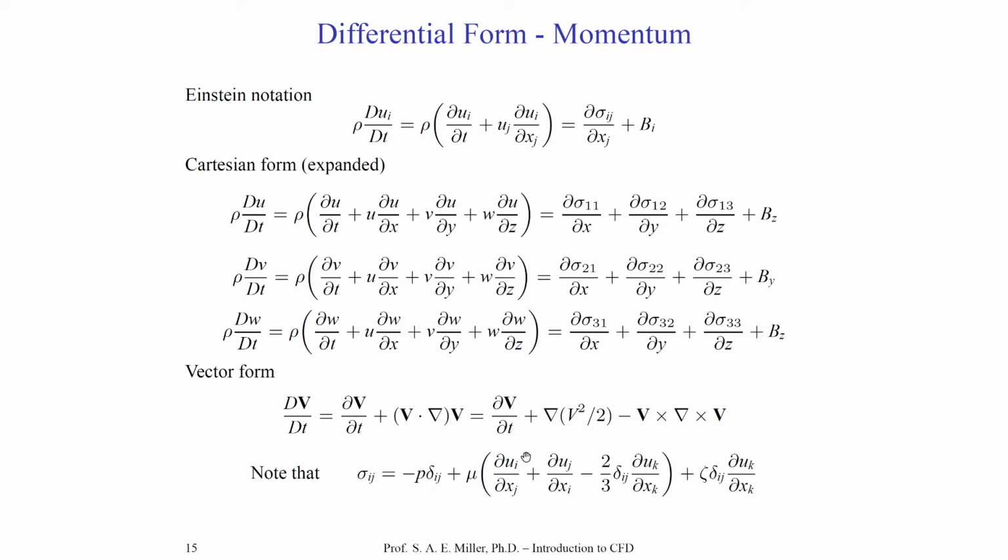Notice the Kronecker delta function does not appear in the second term and appears in the third. So you can imagine that the diagonal terms of the stress tensor in the form of the Navier-Stokes momentum equation would be much more complicated than the off-diagonal terms. Recall the D'Alembert condition. Do you remember what it is? It is the incompressible condition, essentially. Here, that means that partial u partial x plus partial v partial y plus partial w partial z would be equal to 0. Now you'll see we have k summed in this term. We would sum k from 1 to 3. So this term would correspond to the D'Alembert condition. So would the last term in our system of equations.